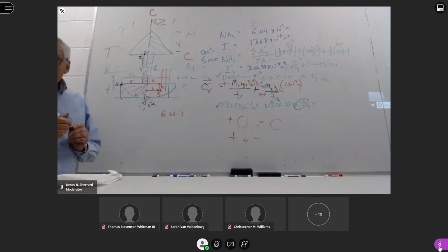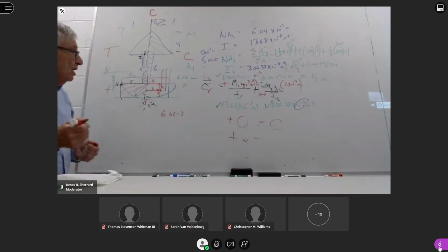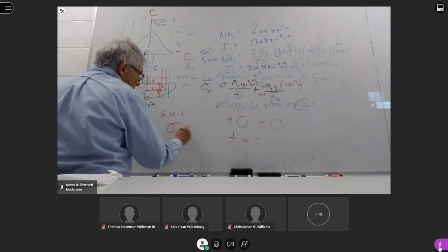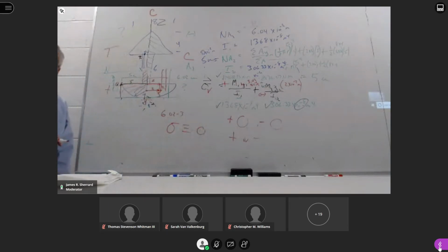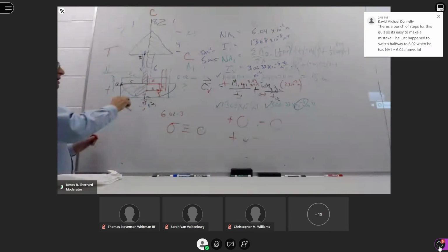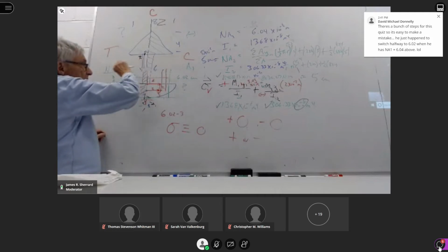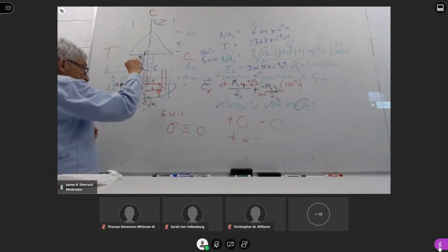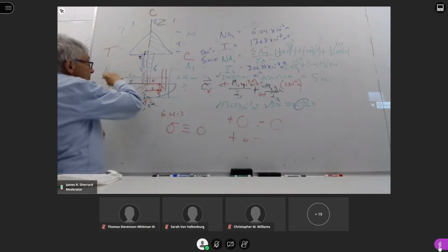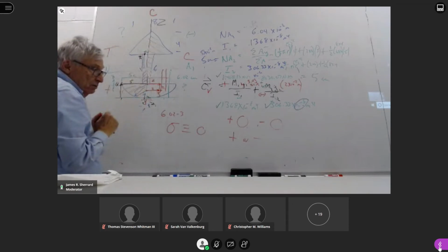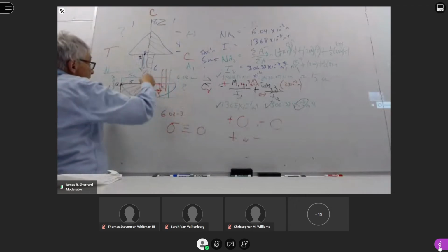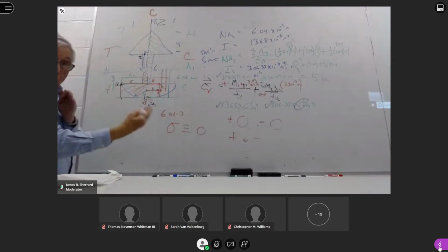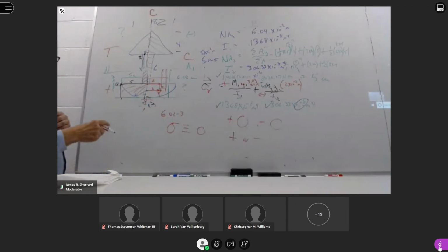And then the final question for extra credit was, where is the plane stress exactly equal to 0? The neutral axis, which remember is actually a plane, is where the plane stress is 0 for this orientation. When we rotated it, this neutral axis, which is also a plane, defines where the plane stress is 0.